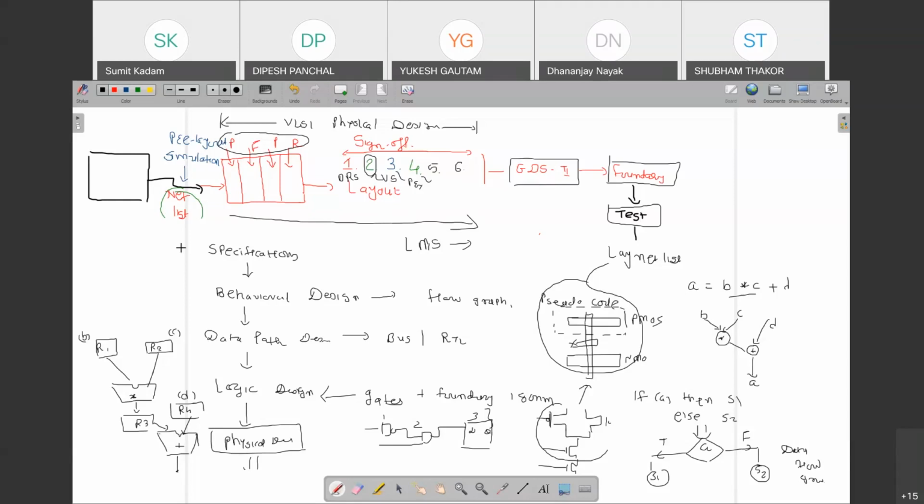So this is your initial specifications and your VHDL, Verilog, that kind of stuff. Logic synthesis, functional verification, whether your gates are working based on your requirement or not. Whenever we start Cadence Encounter, we'll start with this initial step also. We generate some netlist, we simulate like your VHDL Verilog code, and then we take it as an input for our next steps of the physical design.